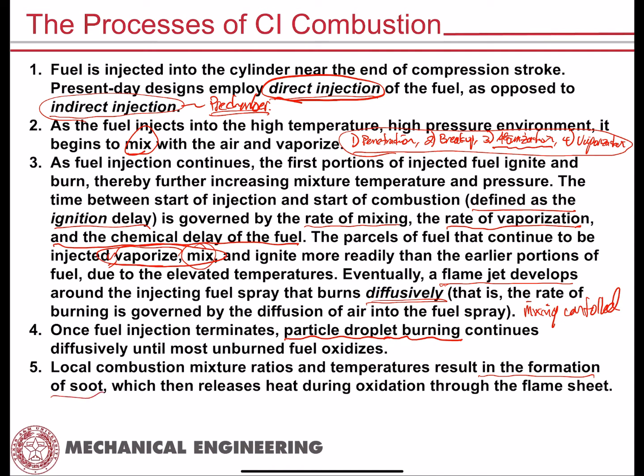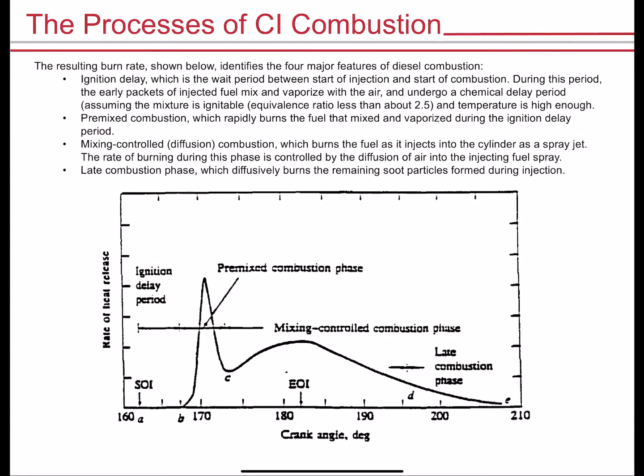That leads to the formation of soot, right? And then that will sometimes burn through the oxidation, through the flame sheet. But of course, you won't be able to oxidize all of that soot, and you'll have some emission of soot or particulate matter from the engine, as we had described earlier in today's lecture.